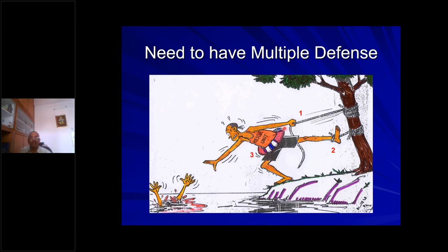If you provide ductility in the structure, even if the structural elements are subjected to a lot of forces, extreme conditions of forces, the ductility will come to the rescue of the structure. So the intention of the code is that a building needs to have a multiple defense system, by way of increasing indeterminacy, by way of increasing ductility, etc. This is the code's intention.